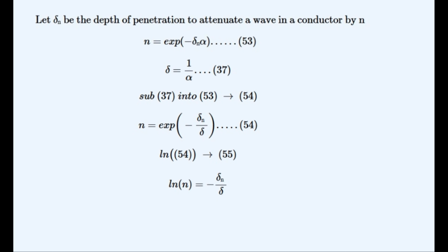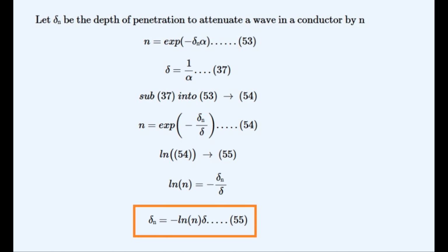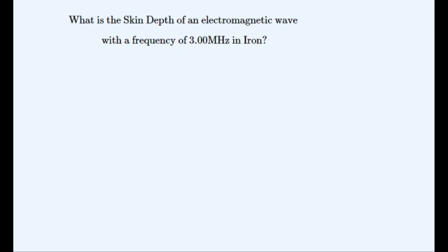And taking the logs of both sides gives us this. And rearranging this equation gives us this equation that we can use to find this penetration depth from the skin depth. And now to use these equations to solve some sample exam problems.